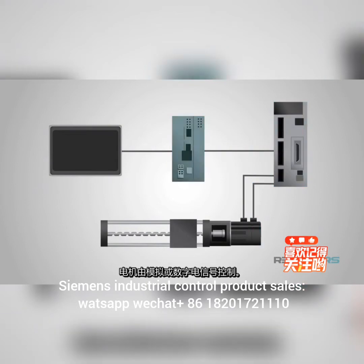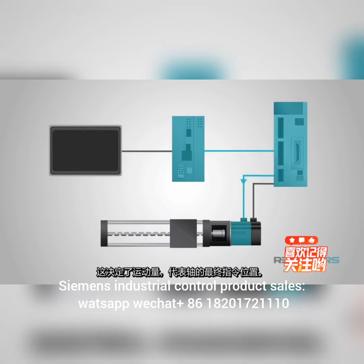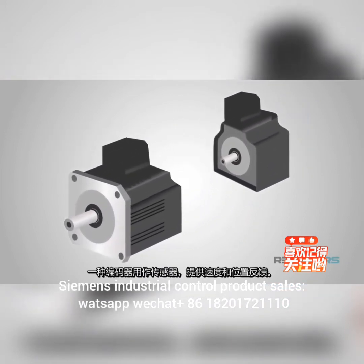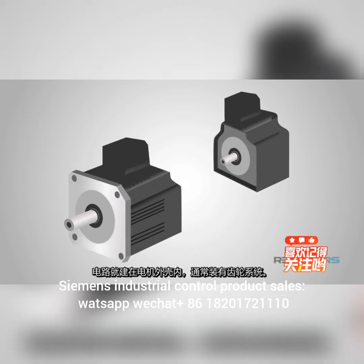The motor is controlled with an electric signal, either analog or digital, which determines the amount of movement, which represents the final command position for the shaft. A type of encoder serves as a sensor providing speed and position feedback. This circuitry is built right inside the motor housing, which usually is fitted with a gear system.